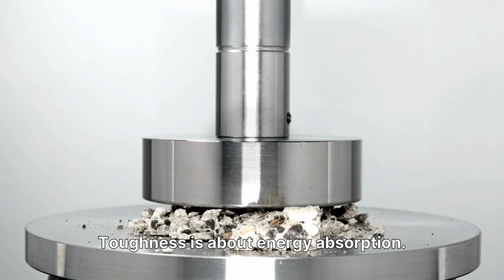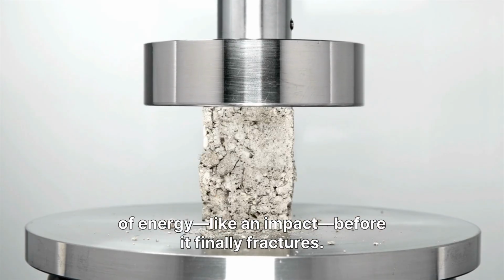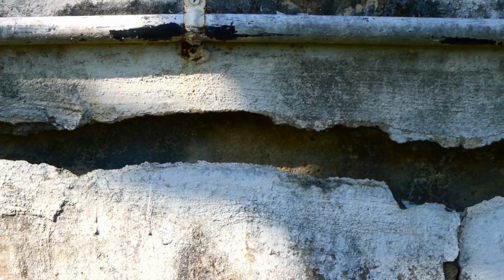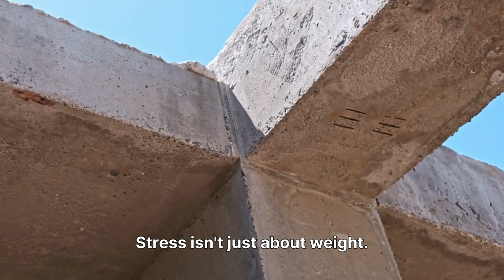Toughness is about energy absorption. A tough material can absorb a lot of energy, like an impact, before it finally fractures. We want materials to be ductile, meaning they give plenty of warning before failing, rather than brittle materials that snap instantly.